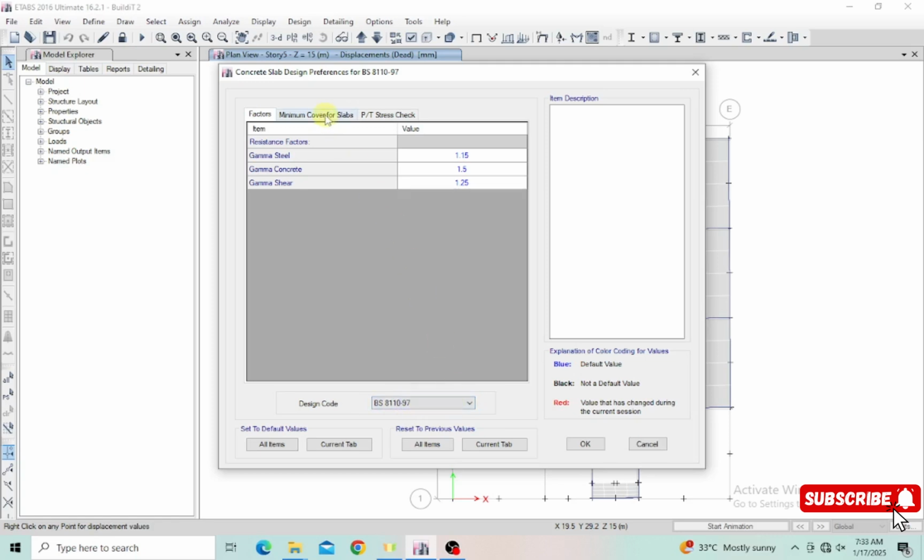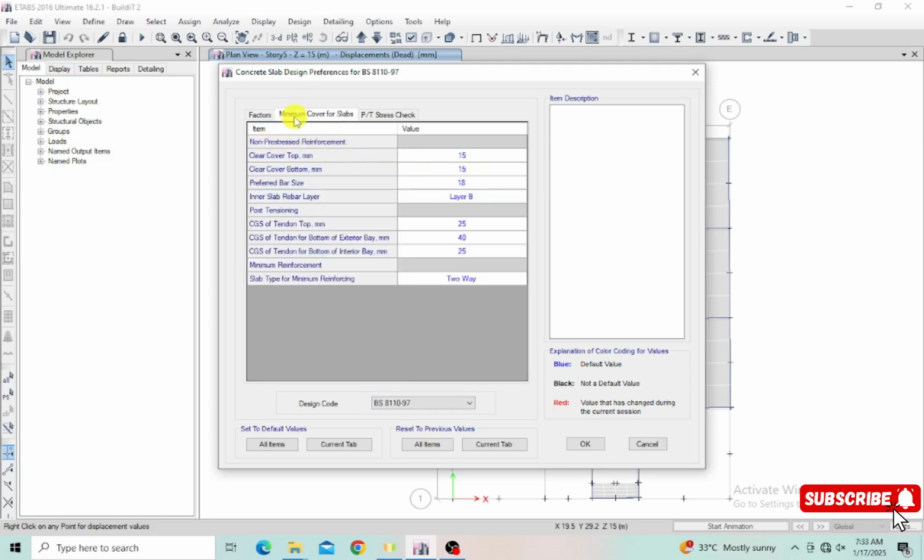Also, these are the safety factors for steel and concrete. These are just going to be the same. And also we have clear cover for the top. You can change these values. These are the preferences, so maybe let's say 20 mm. Then the preferred bar size, maybe let's say 12 mm. It will show in red, signifying that you've changed the value. The value has been changed during the current session, so it turns red when you change the value.